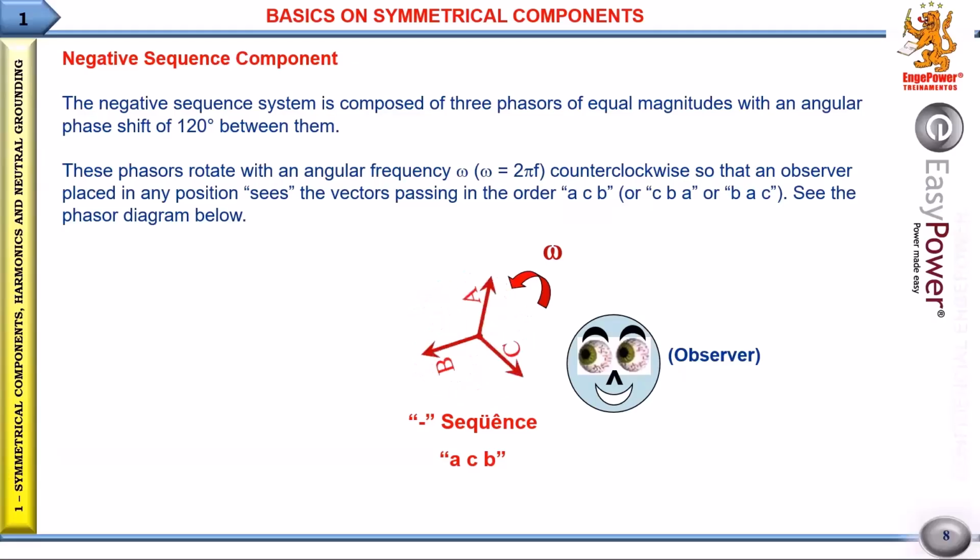After this explanation, it's easy to understand that positive sequence current generate accelerating torques in a motor, whereas negative sequence currents generate restraining torques. When this happens, it's just like increase the load in the motor, which means increasing the current. Increasing the current, the motor will overheat.